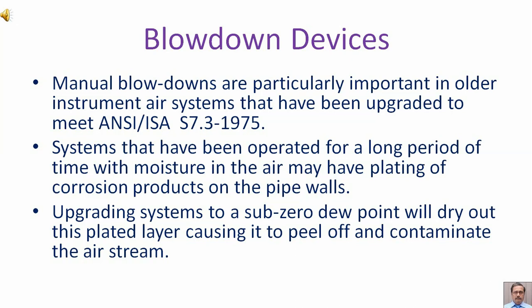Systems that have been operated for a long period of time with moisture in the air may have plating of corrosion products on the pipe walls. Upgrading system to a sub-zero dew point will dry out this plated layer, causing it to peel off and contaminate the air stream.